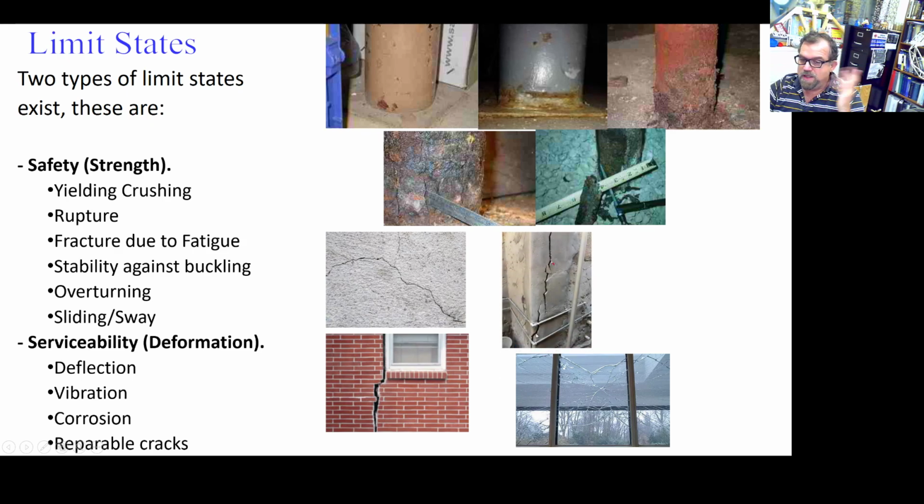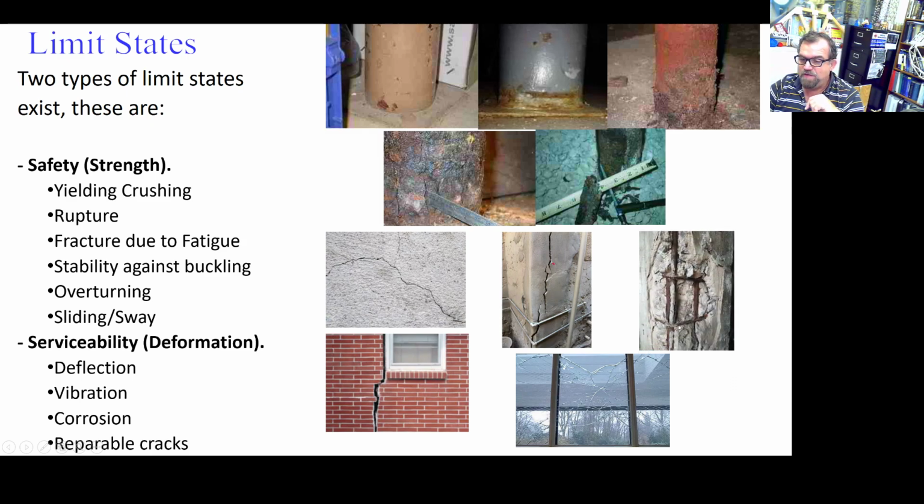Is that important? Is that reparable? Once again, you do not know, but the crack itself is not the problem. But when you investigate that and you find that, then you go back into the corrosion problem, and here you can see that the main steel is being deformed and the confinement is being lost, and that is an issue. So some of them will become a safety issue if left unattended. That's basically it.